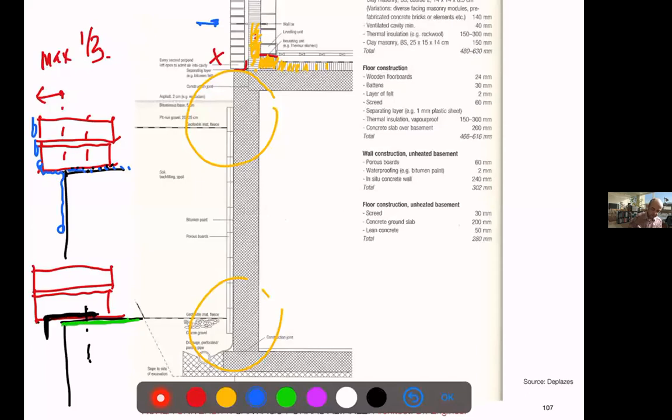So the water now will naturally slide, and we'll have this area, which is the weak point, very protected. And actually you will have a nice view, right, a very clear ending point of this wall with this kind of metal element, which is hiding a dirty joint, which in this case is always on the view, right? You will see it ugly and dirty joint on site.